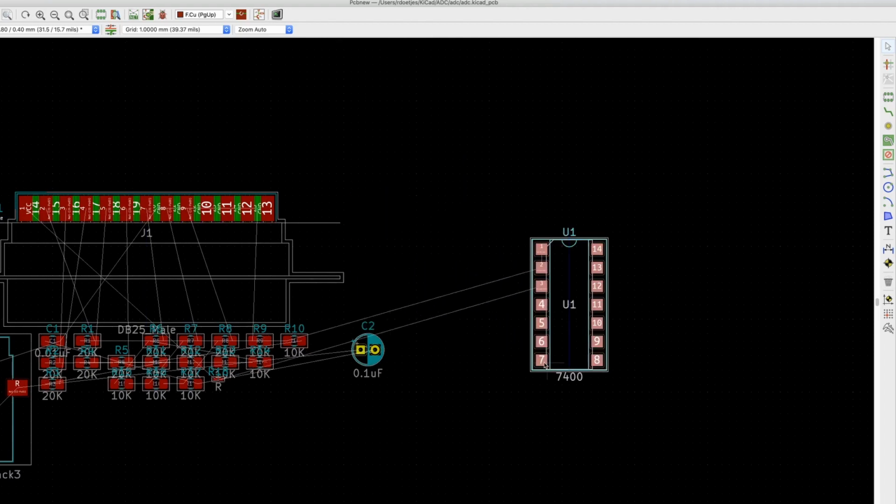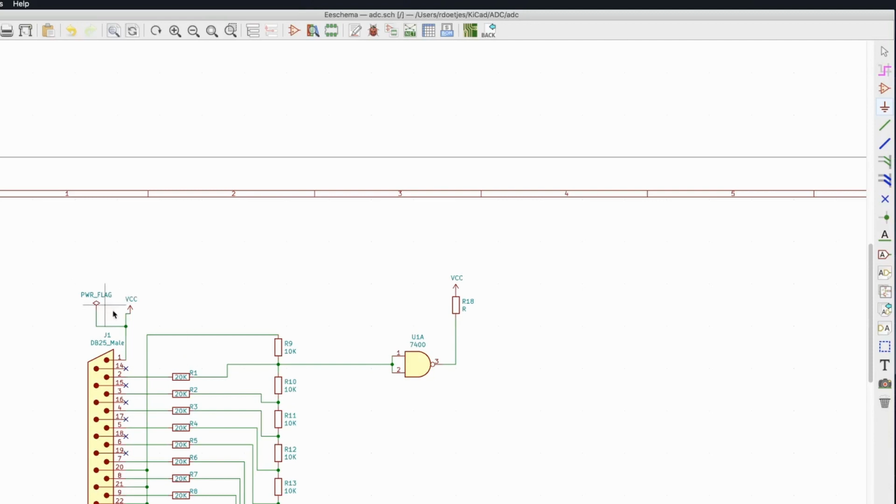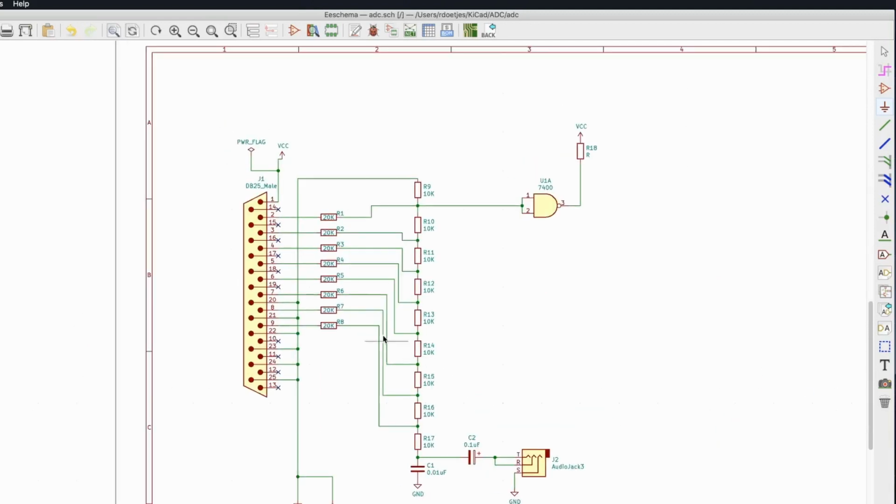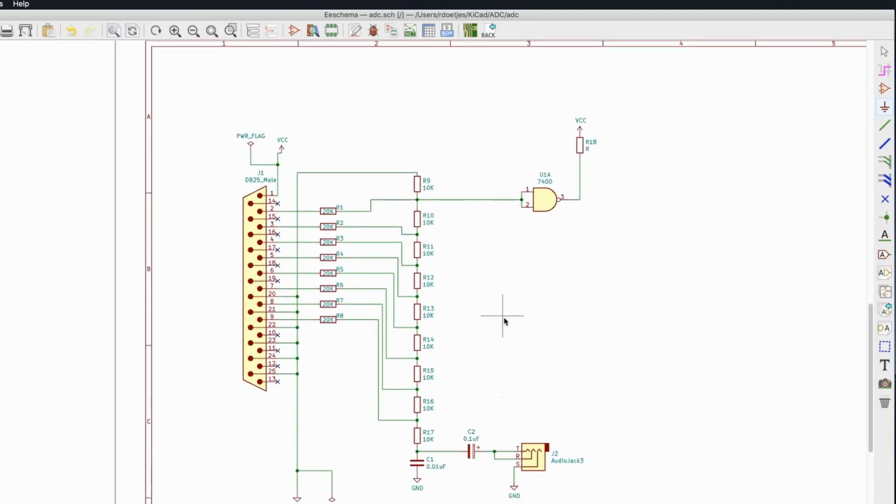If you have any previous experience with these sort of electronics, the TTLs, you know that these are the ground and VCC, and you see they are not connected. Even though we did annotate the board with a VCC and a power flag and a GND and a power flag. This should be enough. In KiCad it is not. In Eagle and OrCAD this works.